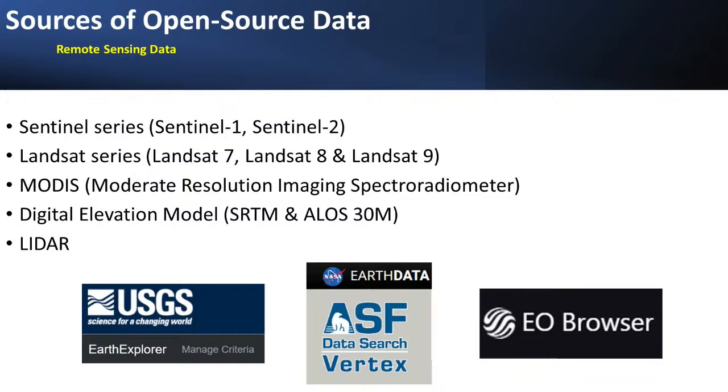There is the Sentinel-1 satellite, which is an optical sensor. No, it is a radar sensor, my apologies. And then you have Sentinel-2, which is an optical sensor. I mentioned these two for this talk because these are the satellites that are widely used when it comes to modeling floods, and also because of their resolution. Both of these satellites are a constellation, which means that in Sentinel-1, there is Sentinel-1A and Sentinel-1B.